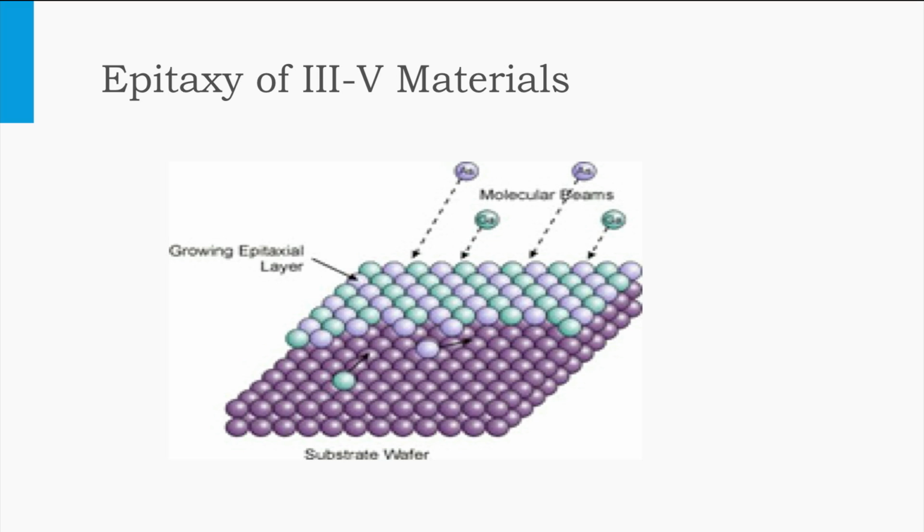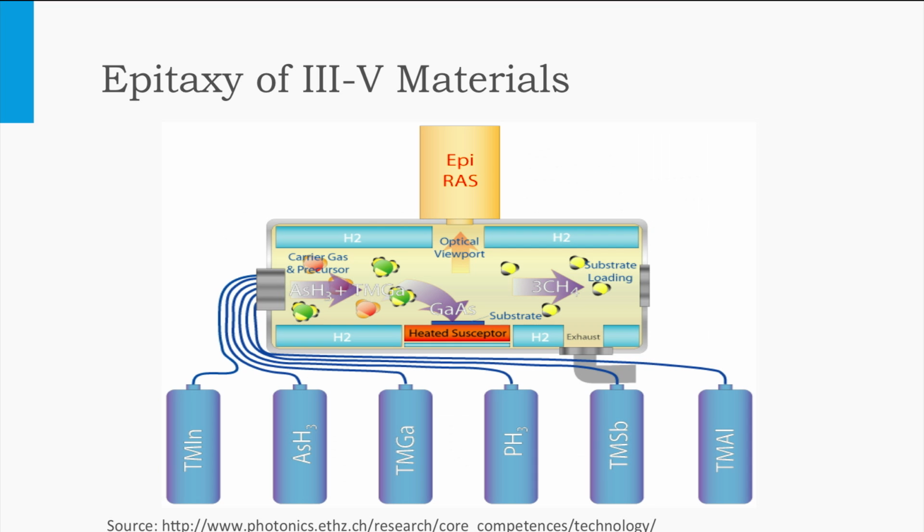The relatively slow layer by layer growth allows the deposition of compact materials without any vacancy defects. Furthermore, processing at high vacuum conditions prevents the incorporation of impurities. Dopants can be added to make it N-type or P-type. 3,5 semiconductors can be deposited up to a very high degree of purity.